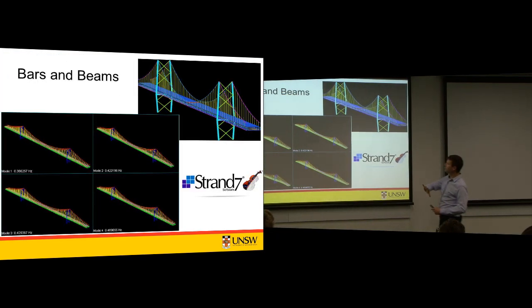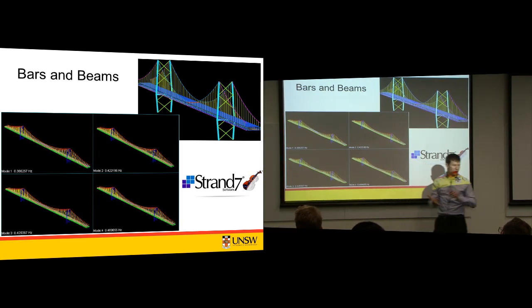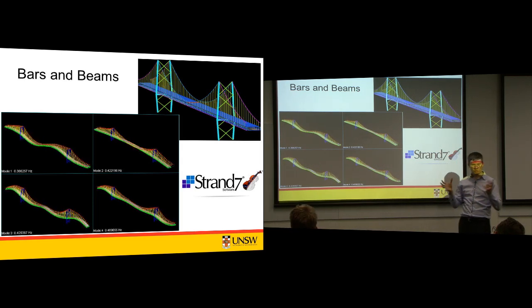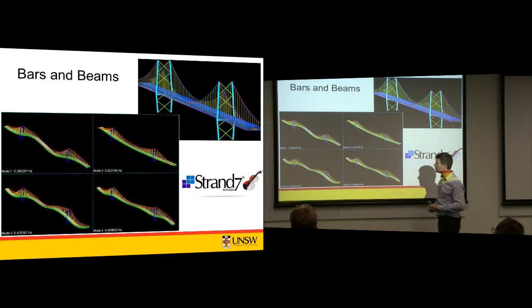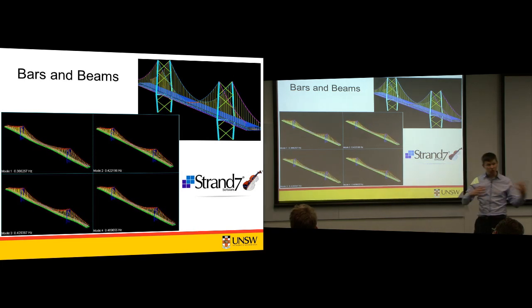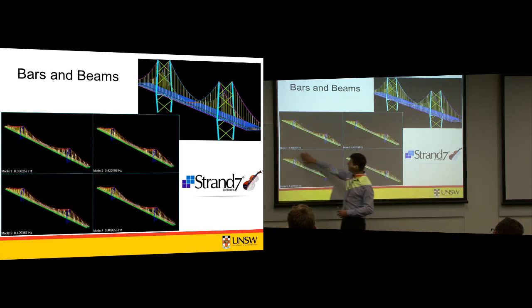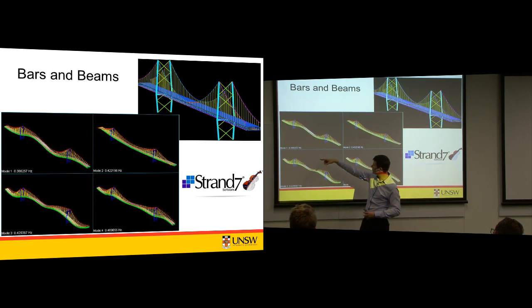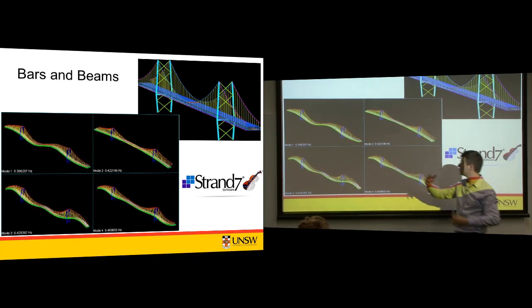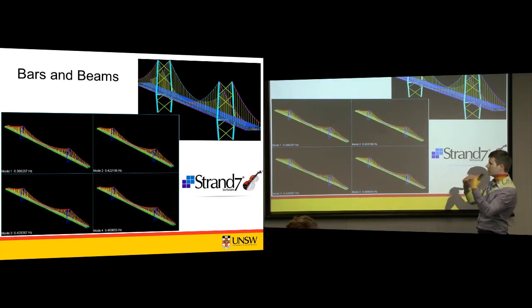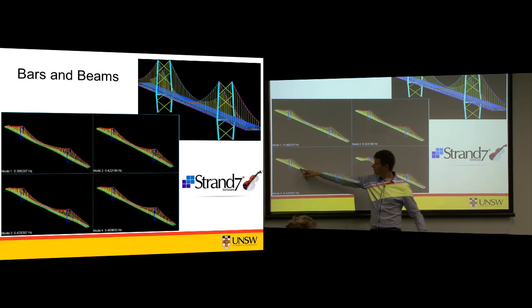And over here, we are doing what's called a modal analysis. So the question is, at what frequencies will the structure vibrate fundamentally, given its nature, and what will that vibration look like, the mode shape, okay? And we care about low frequencies here. Typically, the lowest frequency is 0.366 hertz, for example, and it will shake like that. At about 0.42 hertz, it'll start to shake laterally, all right? About 0.5 hertz, it picks up an inner node and so forth.